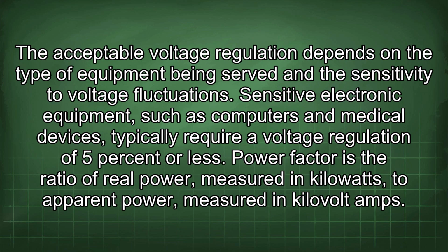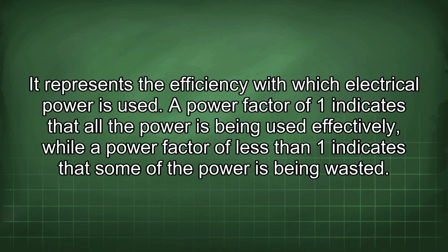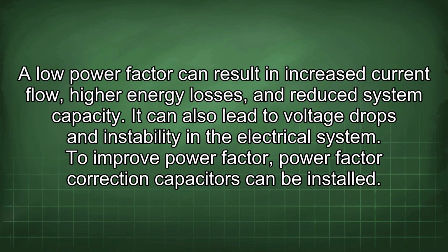Power factor is the ratio of real power, measured in kilowatts, to apparent power, measured in kilovolt amps. It represents the efficiency with which electrical power is used. A power factor of 1 indicates that all the power is being used effectively, while a power factor of less than 1 indicates that some of the power is being wasted. A low power factor can result in increased current flow, higher energy losses, and reduced system capacity.